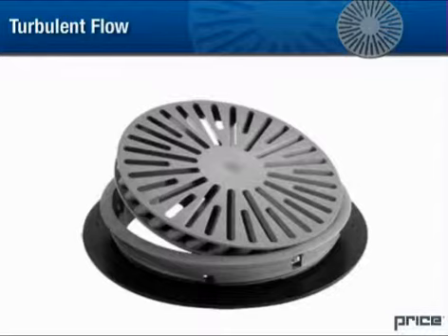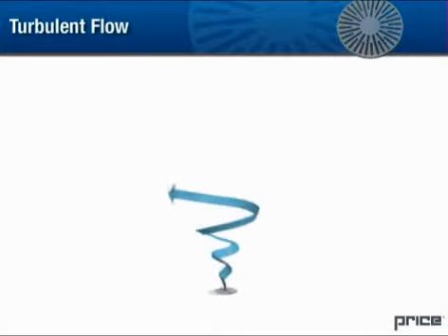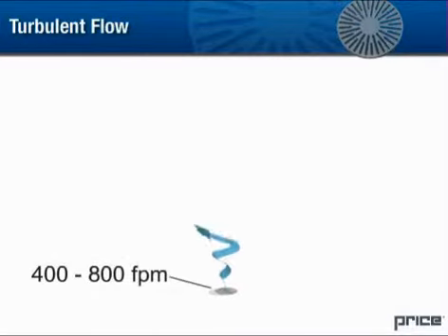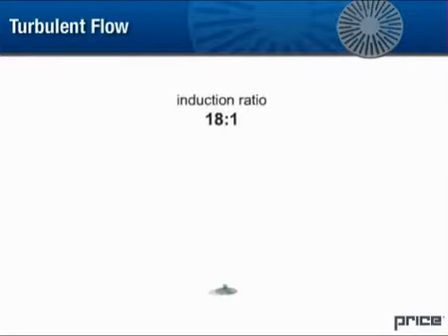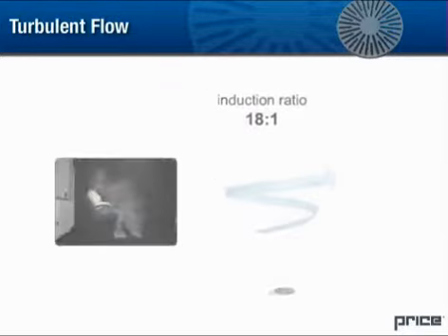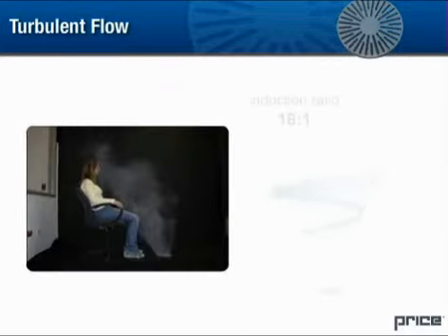An underfloor air distribution system uses floor twist outlets to generate a turbulent airflow. These turbulent flow diffusers discharge conditioned supply air at elevated velocity, around 400 to 800 feet per minute, at floor level. The discharge is a vertical swirling pattern which rapidly induces the room air. This turbulence enhances the induction of room air and allows occupants to be in close proximity to the supply air